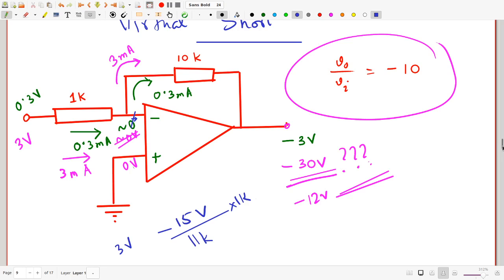So, as I pointed out, it is a huge open loop gain of the op-amp which makes virtual ground possible. And we have demonstrated once a while ago how to analyze the circuit taking into account the huge gain of the op-amp. But from this point on, we are going to assume that the op-amp is ideal, the huge gain really is infinite, and Vd is really zero. Well, it's not really zero, but it's close enough to zero for all practical purposes. Just to stress once again, the caveat is you're assuming that the op-amp is in the linear region.